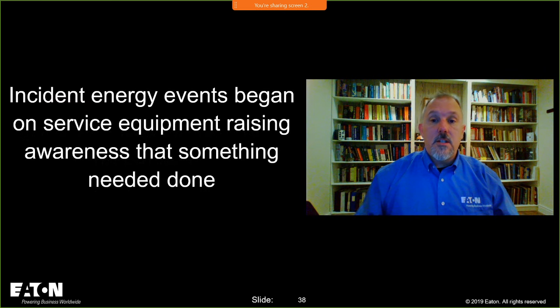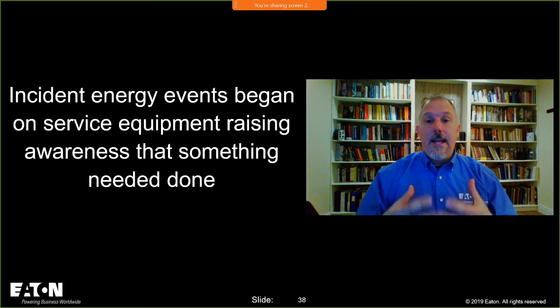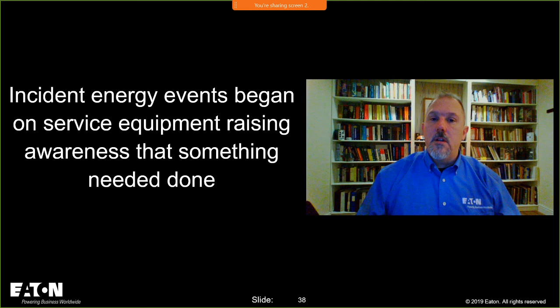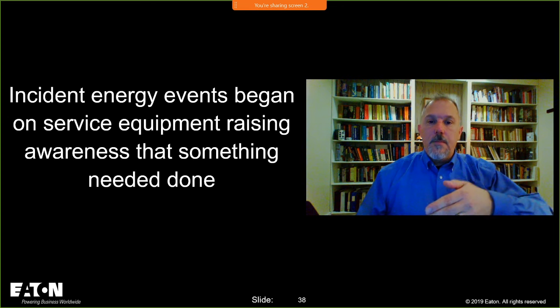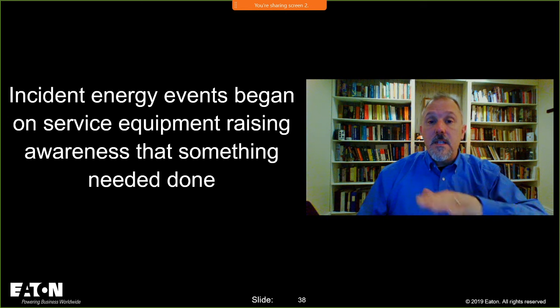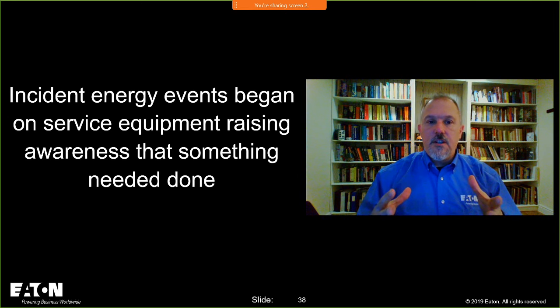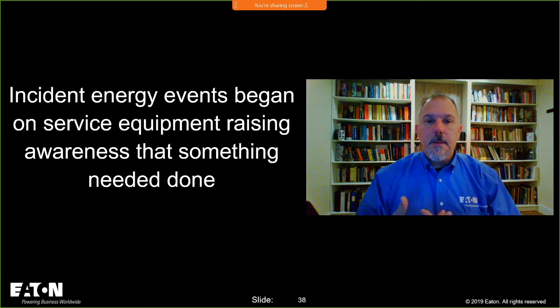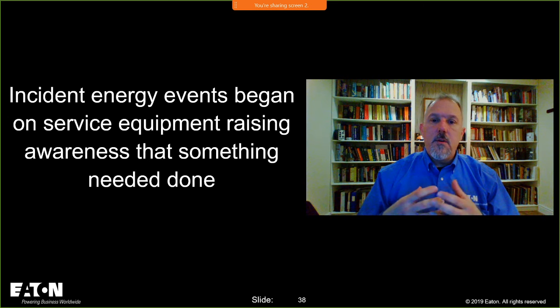Incident energy events started to occur because I had a delay in the ground fault protection of those larger breakers at the service entrance equipment. We had examples of burn downs on service entrance equipment. If you look back at the public inputs and public comments for the 1971 code, you'll see all of those arc flash events. There are some good IEEE papers written around this topic. And that's how ground fault protection of equipment came to be.